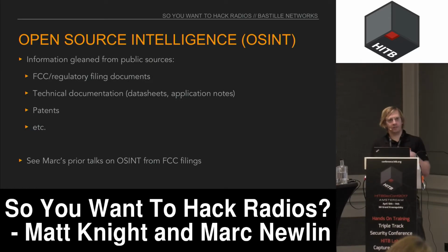With the FCC in the United States, it's quite handy because it has a very verbose amount of information for each device. So if you're selling a device in the US, you send it to a test lab, the test lab operates the device, and the test lab will put together a test report with a lot of physical layer information about how the device operates. So if you're looking at a device which is sold in the US market or sold in the US plus other markets, you can look up the device on the FCC website, pull down this test report, and that will tell you oftentimes the modulation and all the channel characterization you need to know about the device.